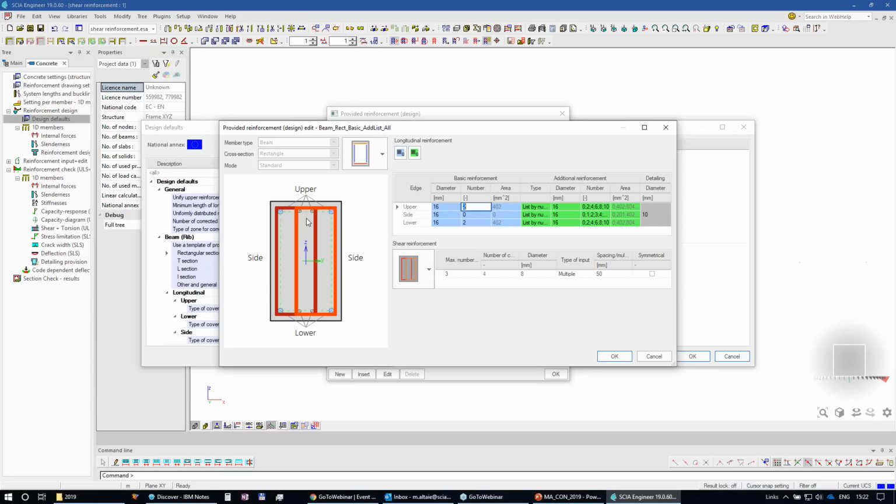So if you would like to compare MED with MRD, keep in mind, if the bars are gray, then they are not used. The best scenario in that case, if you would like to use this shape of the stirrups, instead of 2, use 4 bars. And then those bars will be used for the calculation of the MRD. I think it is now clear for you.